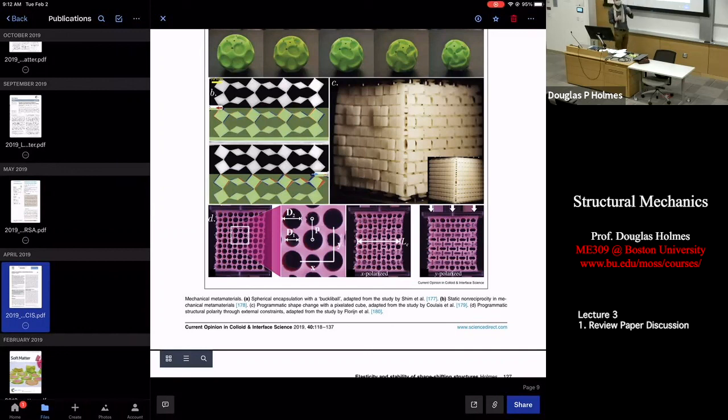And so people have been engineering negative Poisson ratio structures by playing with geometry. Foam is much smaller than these. These are literally like this big. These holes are probably, I don't know, the size of your fingernail, and the structure itself is probably this big here. So you can engineer these things on the macro scale to get a bulk behavior that is usually prescribed on the material scale. Does that help a little bit?